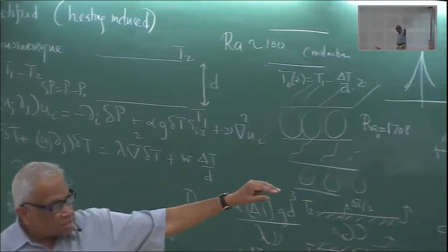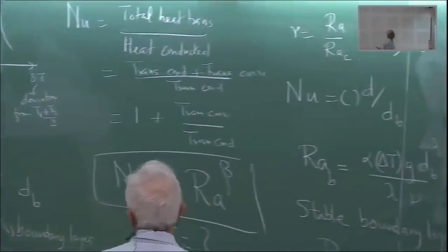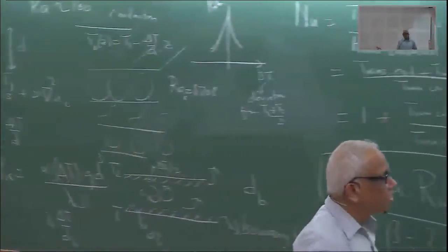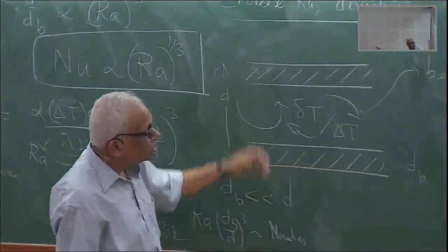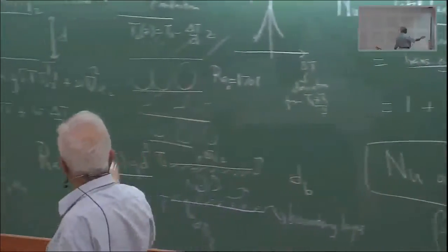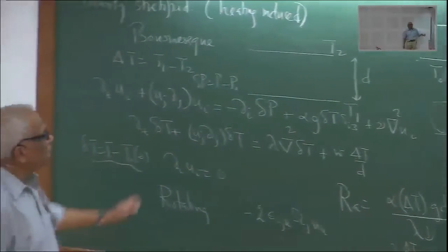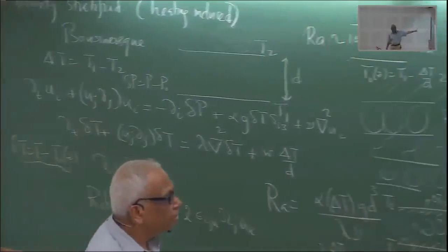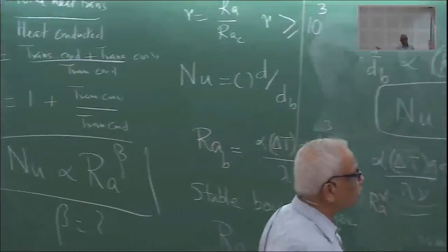Inside, in the middle of the cell, the viscous terms, which have this del square over here, are once again operative near the boundary, at the small scales that we have been talking about. So viscosity is at small scales, and you don't want to worry about this. The nonlinear velocity term has to be the big one, because it's a turbulent motion inside.